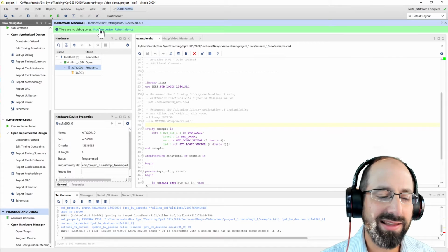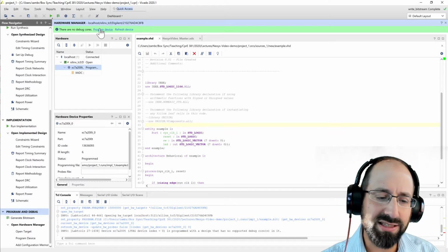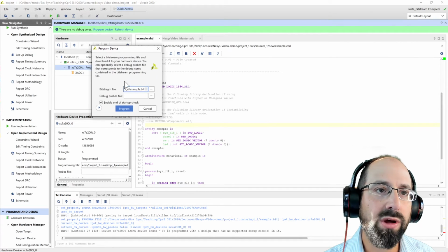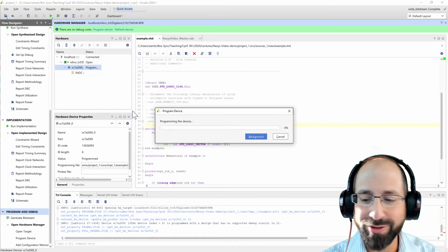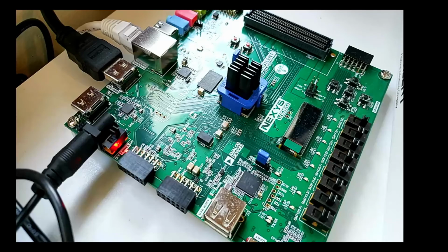So I'm just connecting to the device. It refers to it as a hardware server. That's a Vivado specific thing. It's just a USB driver right now, like anything else. I'm going to tell it to program that device with the bit file that got generated, the binary blob that got generated. And it shouldn't take that long. It is a relatively large file, so it takes a little while to actually program here. And so we have our new design that's now running on that device.